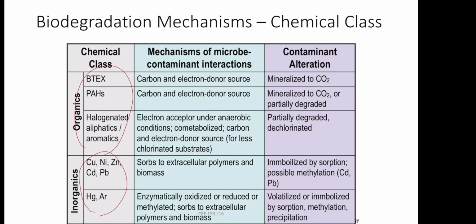Again, you need nutrients and all types of microorganisms. So that's a little bit more complicated. But the key here is oxidation or reduction, because microorganisms can both oxidize or reduce. So you have to think of that. Anytime halogenated organic compounds, halogenated means chlorine, bromine, all that, they're already at group 7 of the periodic table. So the only way for them to be removed from the system is by accepting electrons. So anytime you see a carbon-chlorine bond, the only way to treat it is by reduction, not oxidation.